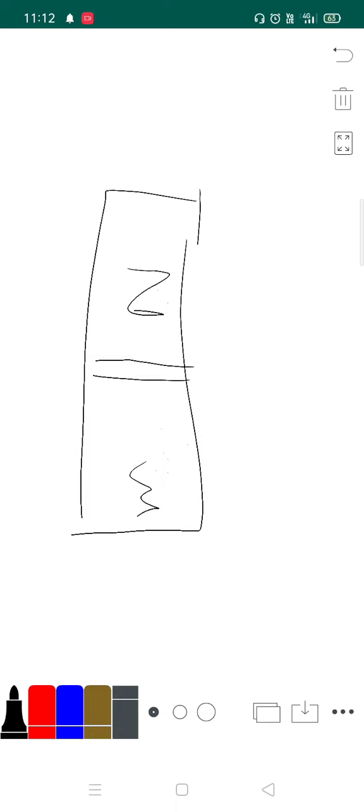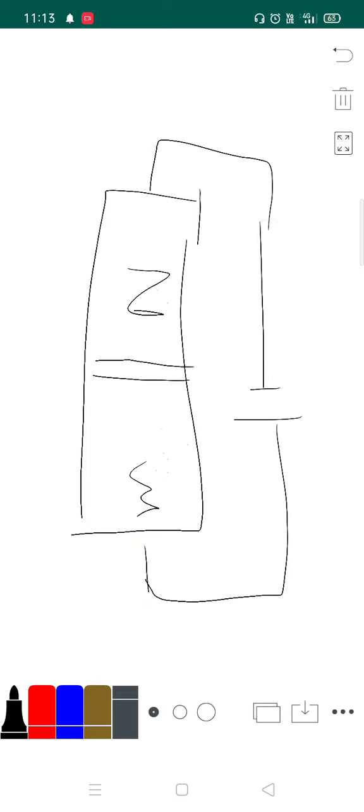So when we connect this diode in the forward bias condition, the electrons are attracted to the positive terminal of the battery. So electrons will flow from the N-type to the metal. So there is a flow of charge carriers. Again, electrons in the N-type try to move into the metal. In this way, the flow of electrons is established.